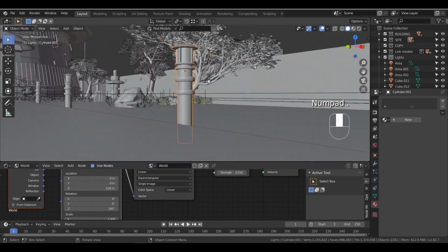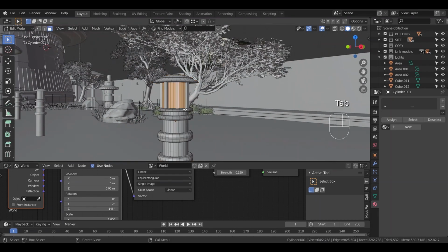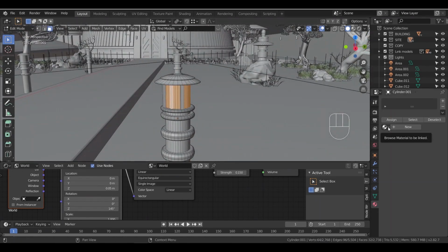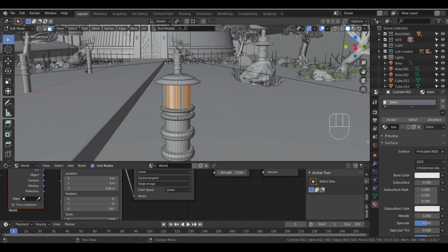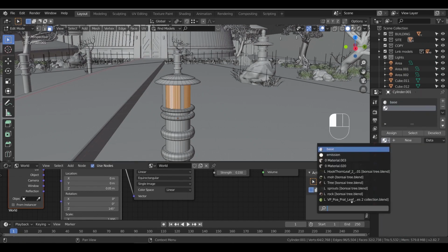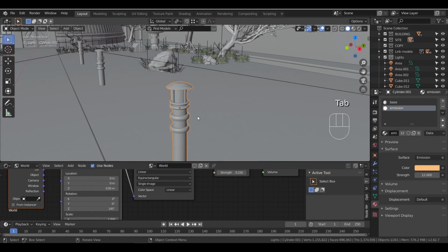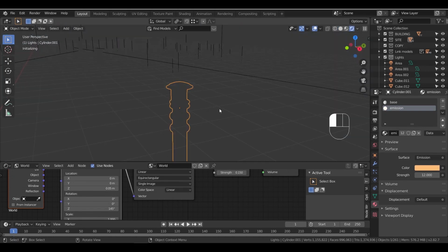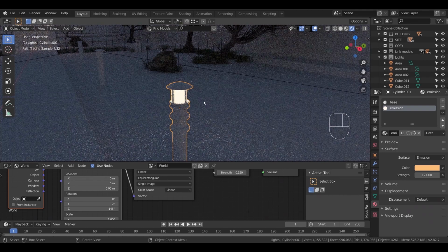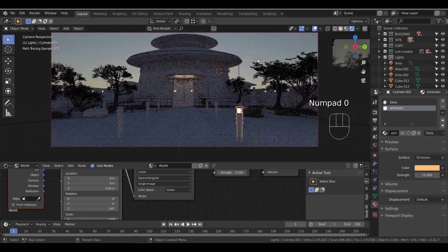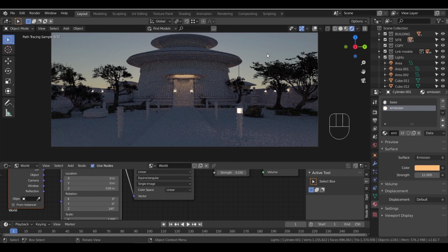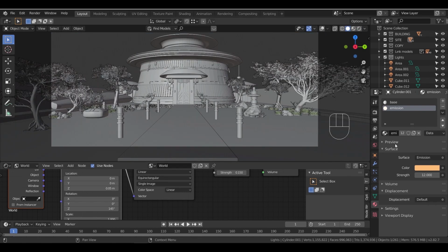Now, in this model, select those faces, and as before, we will add the same two materials. First one is base for the model, the second one will be the light, and we will assign those highlighted faces to it. To increase the light strength in this model alone, I will hit the number near the material name as shown, and change the strength after that.